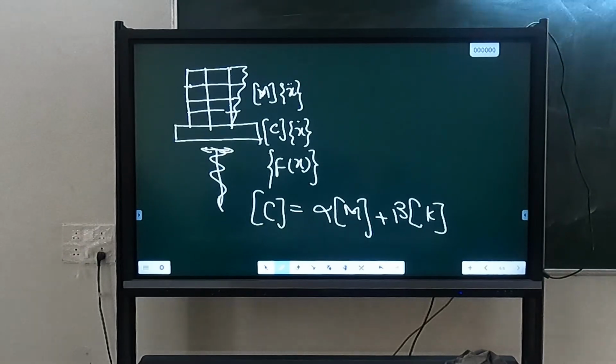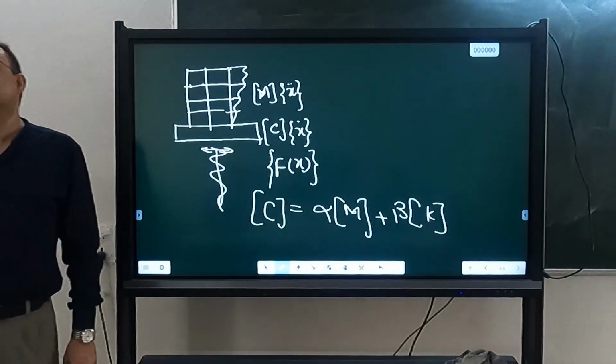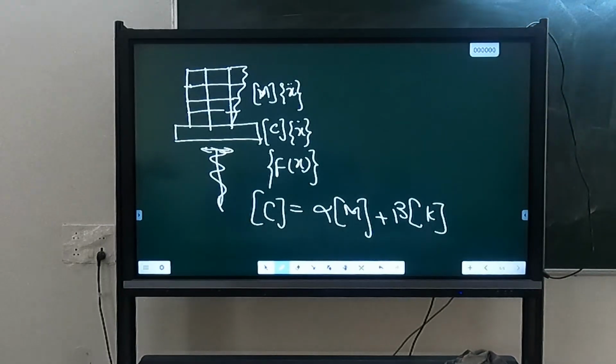So first of all, you have to construct the whole structure. Construction itself is costly. Then a shake table of that size. You have seen, we boast about our shake table. We have a shake table, but what types of structures can we test there? Can you test a 3-story building or even this 2-story building there? It's not possible. Only 2 facilities in the world I am aware of. Maybe in China some more might have come, which we are not aware of. But 2 facilities which are very commonly known: E-Defense in Japan and NEES in the US, where they can test full-scale structures like this.